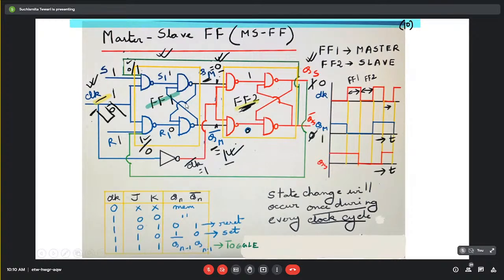If the number of components is increasing, the wire length is also increasing, or more wires are needed to establish a secure connection. Even if we neglect that wire delay, we cannot neglect the gate delay. So with each stage, we are heading for more complexity and more delay. That is, speed is hampering, but we are increasing the multifunctionality also.